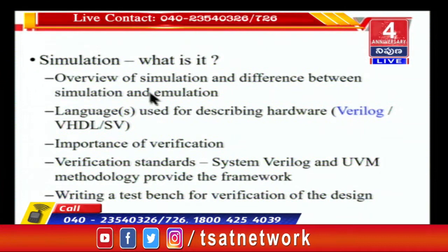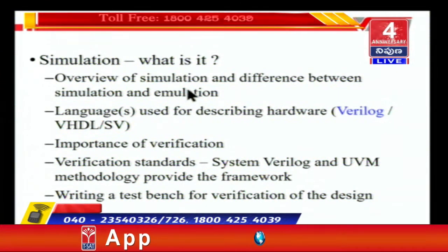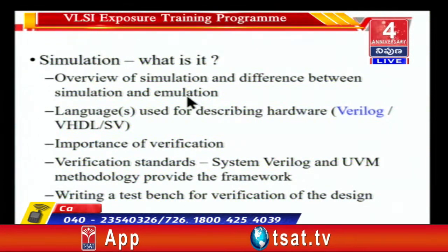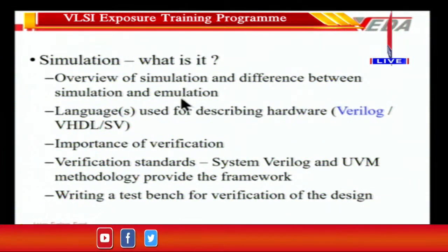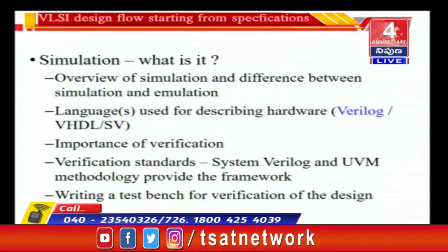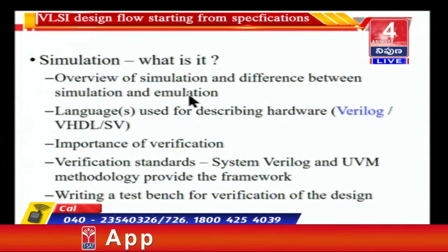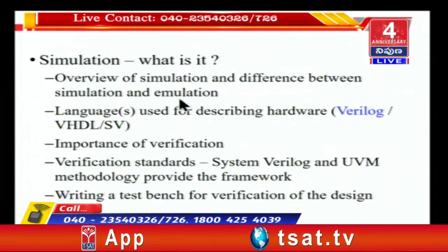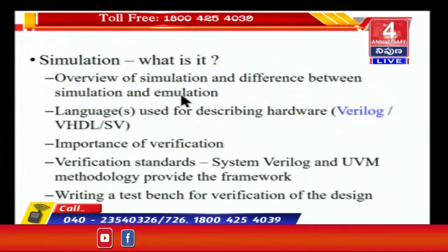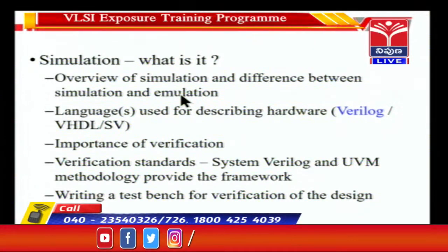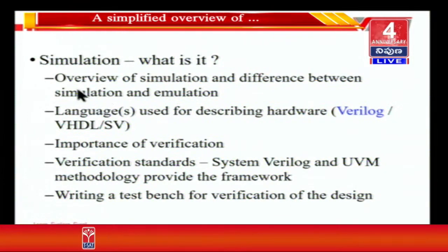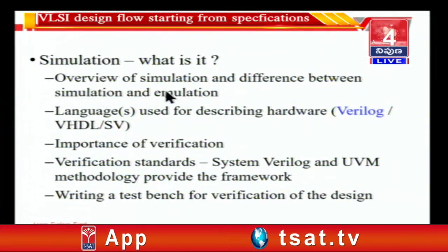The same microcontroller, if you are putting it over here, then you are trying to see whether your microcontroller is working correctly in hardware or not. It is not the ASIC, but it is the FPGA on which your microcontroller is sitting. Sitting means it's residing inside the FPGA, and the FPGA also has a memory. Therefore, this memory will store the instructions for execution by that particular processor. Therefore, the verification of a logic function by making that logic function execute on a different platform is an emulation. Making it execute completely in software is simulation.